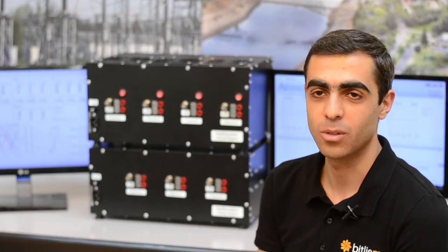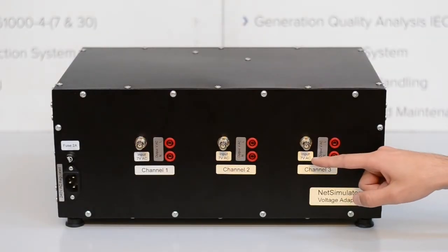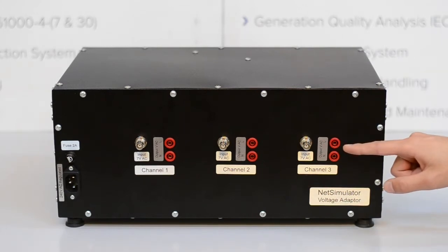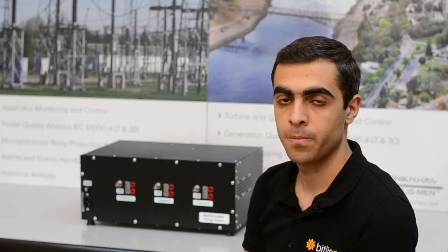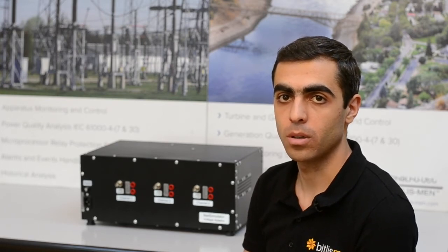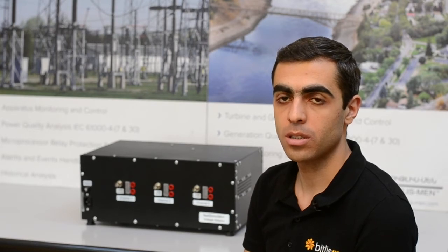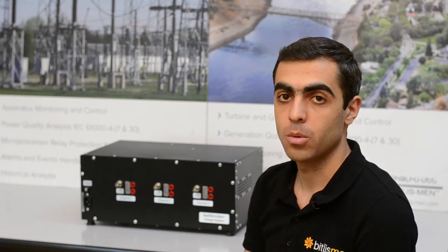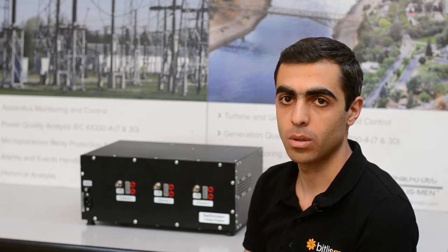Now let's have a look at the voltage adapter. The input accepts 7 volt AC or DC signal, and the output ranges up to 220 volt AC or DC. The adapter converts the input low voltage to high voltage signal. The conversion is done transparently, meaning the high voltage signal will replicate the low voltage signal shape and spectral band up to 64th harmonics within 1% error. The voltage adapter is intended to be used only with measuring devices, which have high input impedance. This means the output of the adapter cannot be connected to a load.